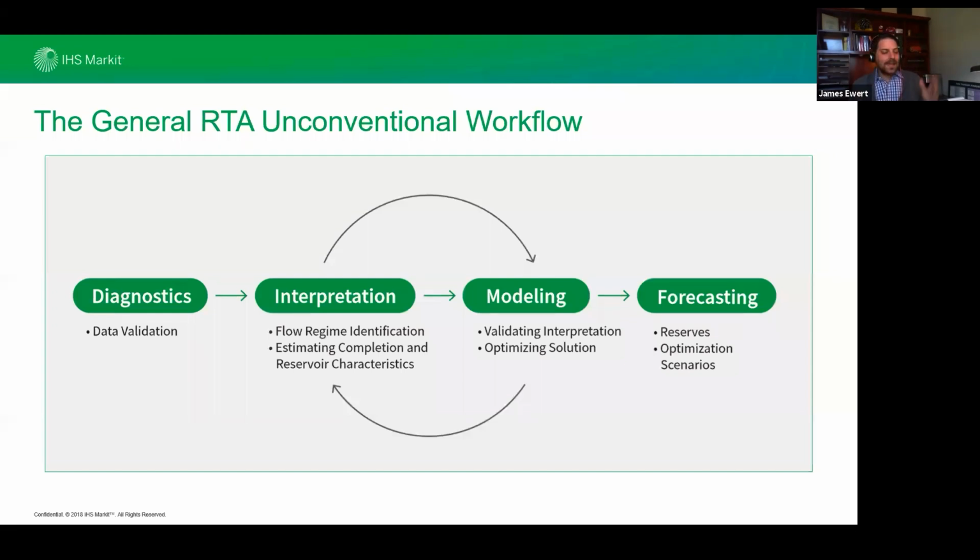Remember, this forecast is based on a physics-based model using values that we got from listening to the data. It's creating a forecast that isn't just drawing a line through data, but is dynamically calculating the equations to come up with that future curve. And that's how you get your reserves. This is how you can start to do things such as what we could refer to as optimization scenarios, where you could say, what if we refractured this well? What if we had produced it at a lower drawdown? All of these different things can be played with once you're in the forecasting.